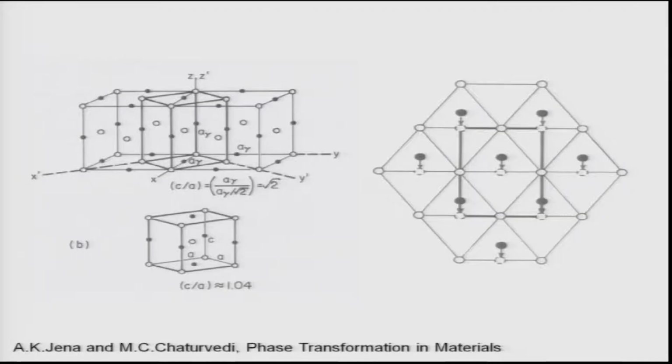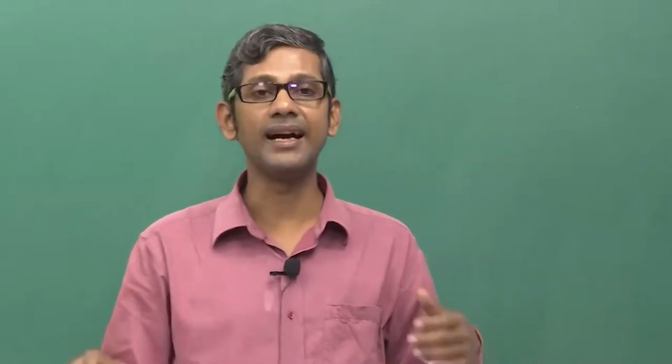As you see here, the carbon atoms move from this position to these positions very easily. So thus the whole distortion requires vertical movement of the carbon atoms. These carbon atoms which I am showing here move vertically simply by application of the shear force, like in this way, and they cause the distortion in the martensitic plates. So that is basically the idea.